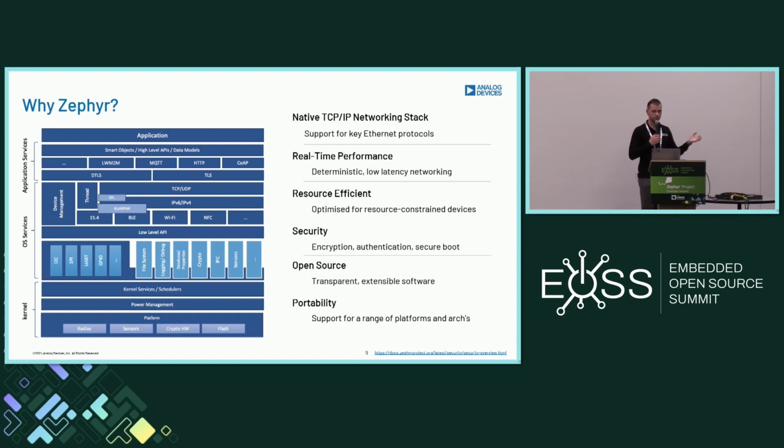So this stack provides support for the key protocols required when enabling a device with Ethernet connectivity, from layer 3, layer 4 network transport layers all the way to various support for layer 7 application protocols. Zephyr's stack is also native, meaning that it was developed specifically for Zephyr, with common memory buffers being used throughout, which is advantageous in terms of reducing RAM usage, which can be an issue when implementing TCP/IP connectivity on embedded devices. The real-time performance is also a factor to consider.